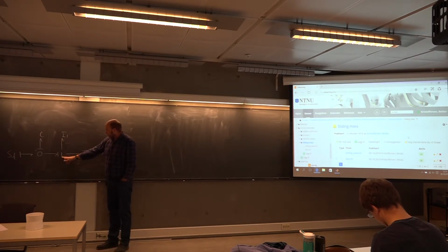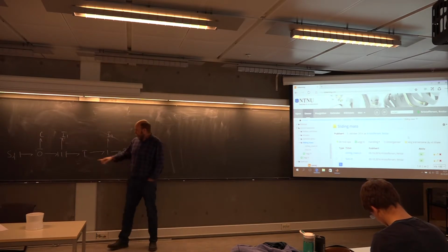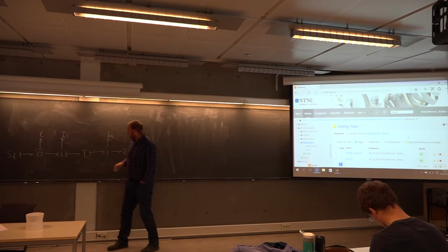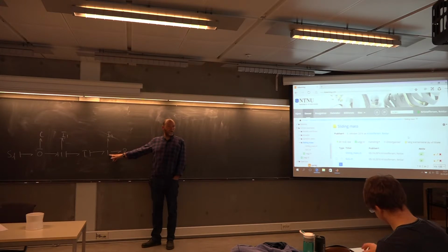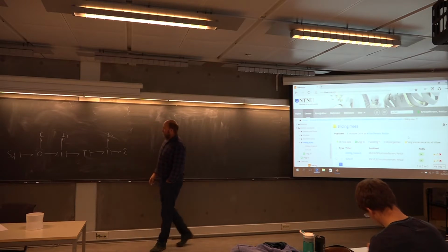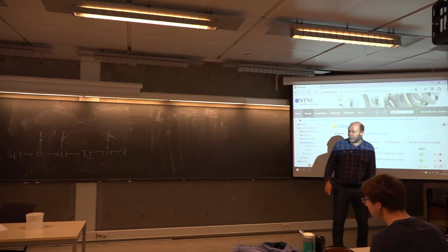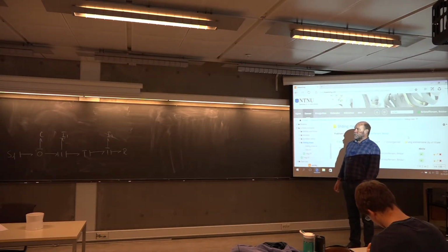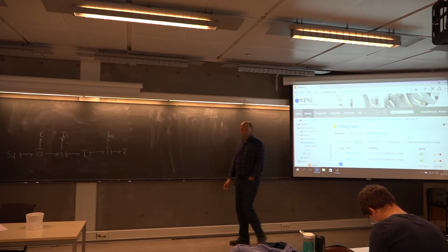That doesn't dictate anything. But I have a mass here, so I choose integral for it. Aha, then the 1 dictates the final stroke here. The transformer doesn't change anything. Stroke there. But then the last 1 junction has got the 1 stroke away from it already. Hence, the final stroke has to be like this. Okay, so this is a differential stroke for the inertance number 2. So this is then what we call an over-causal system.